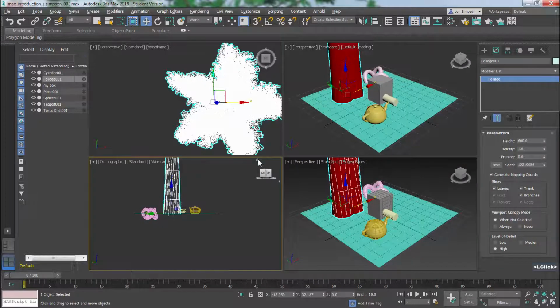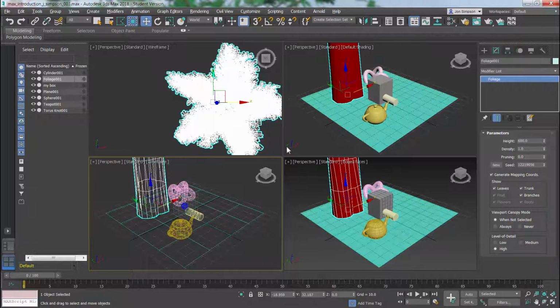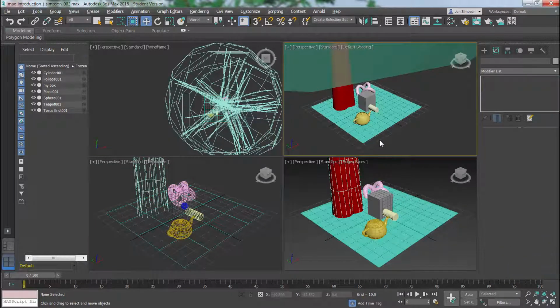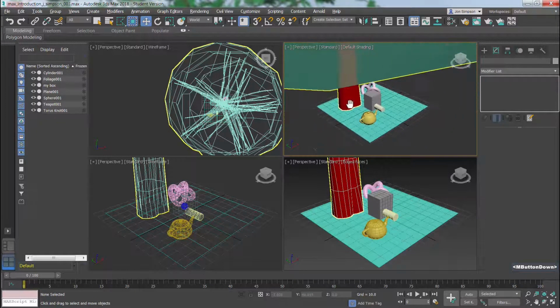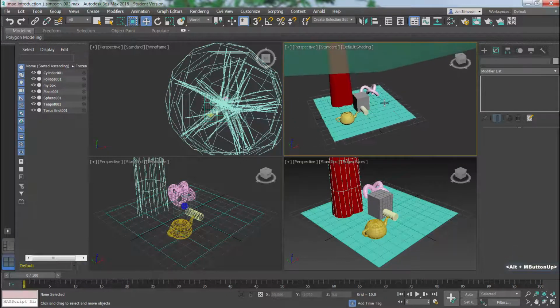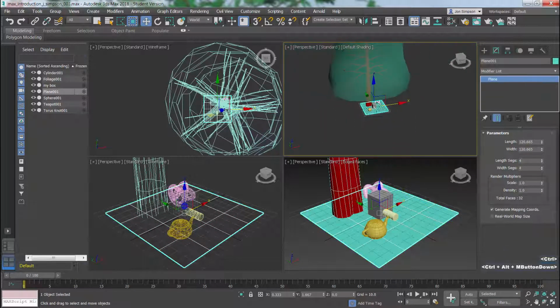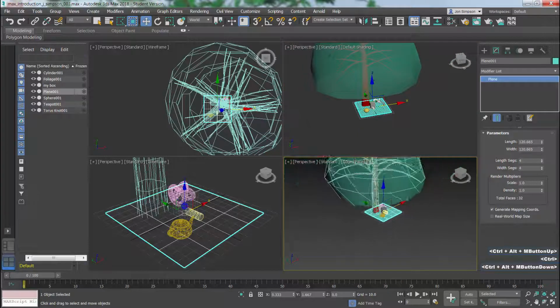We will now explore the shortcut keys for changing the view into the 3D world. There are controls in the bottom right corner for doing this, but shortcut keys will help you work faster. Use the middle mouse button to pan the view. Alt middle mouse to rotate. Alt control middle mouse while moving the mouse to zoom. Scrolling the wheel will zoom as well, but is not as smooth and moves in jumps.